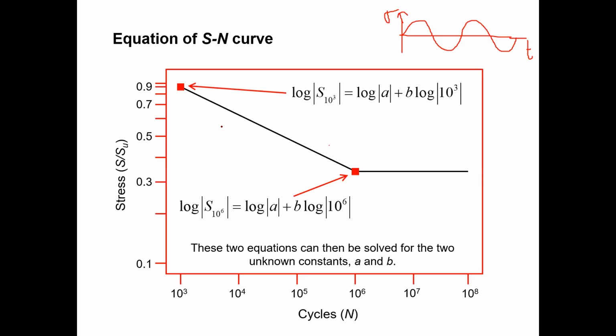You will apply the same force and bend it upward and downward with the same load. You are not going to bend it in a very hard manner. Softly you will bend it a few more cycles, and when you bend it 15 or 20 cycles, it will break, isn't it? Yes, sir. So that is the nature of fatigue. Okay, I understand.